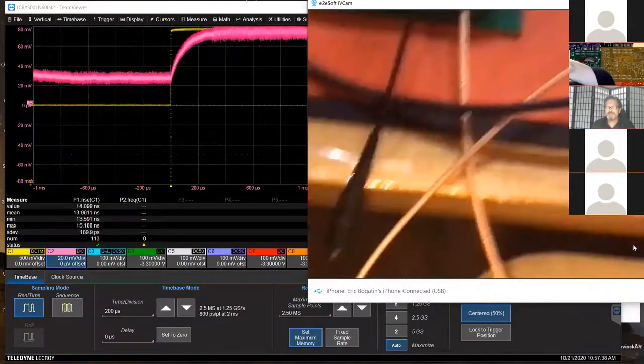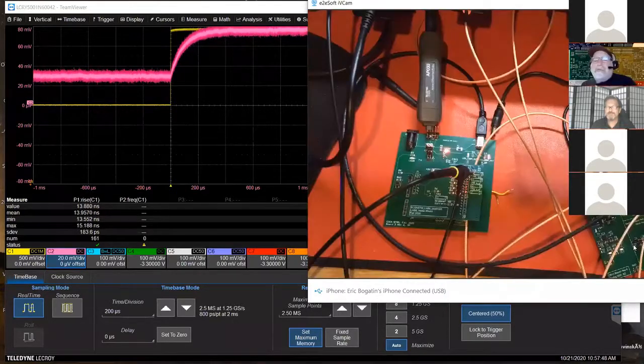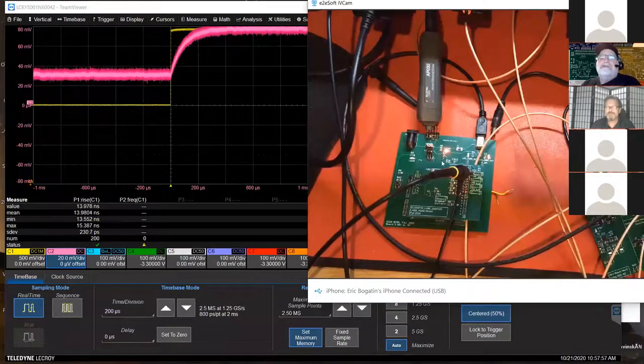The fast currents are coming from locally, the decoupling capacitors, and this slow rising signal here is the current coming through the USB in order to charge up those decoupling capacitors. And that says they're doing their job. They're keeping the high frequency currents off the board, and they're providing the local charge for those fast I/O.